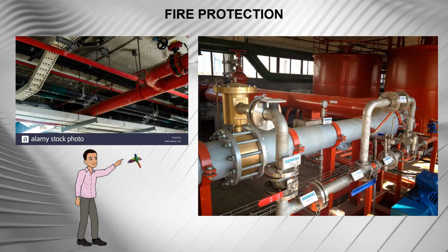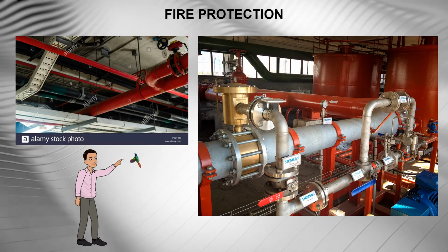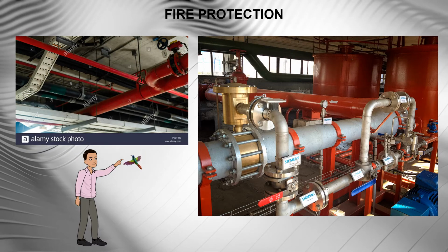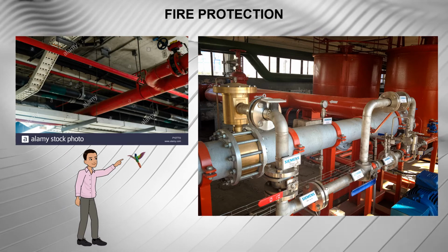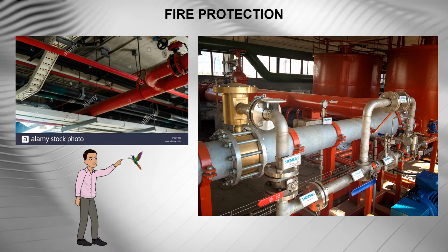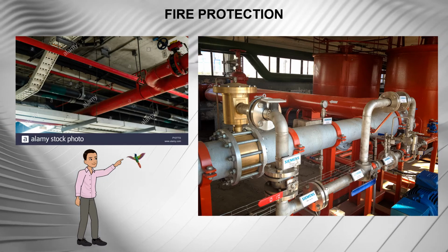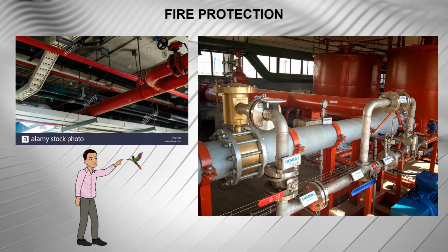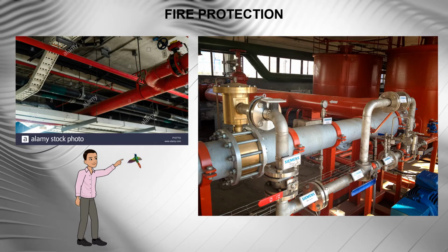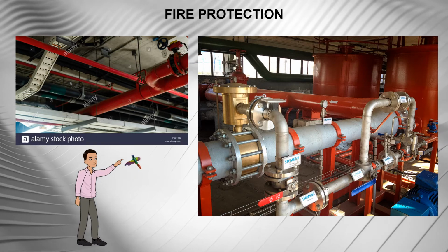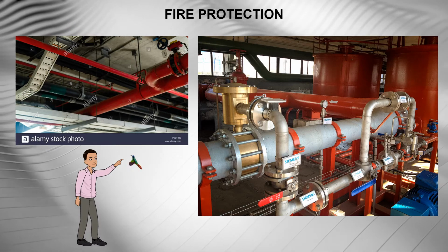Due to the characteristics of the process to be carried out in a special building, it may require exceptional measures in respect of fire and explosion prevention and in fire protection and damage limitation. Sprinkler installation of exceptional capacity may be required, as well as carbon dioxide injection. Dust explosion is a risk in processes dependent on the transport of finely divided powders by conveyor or air duct.